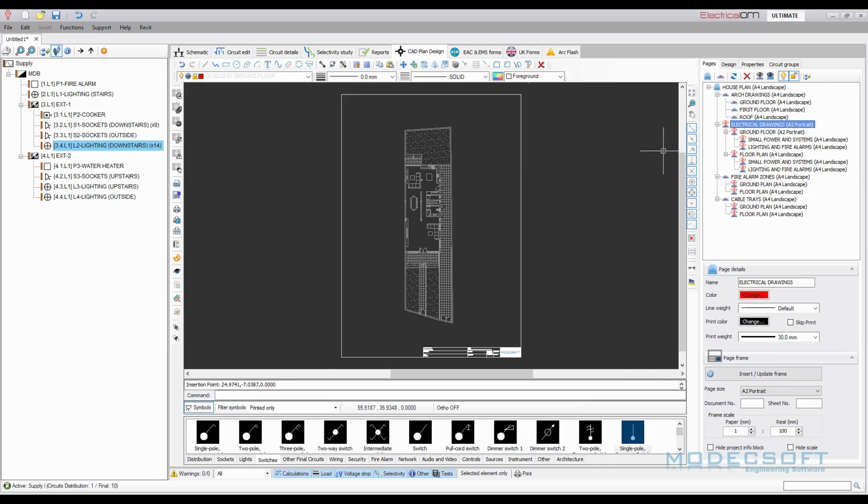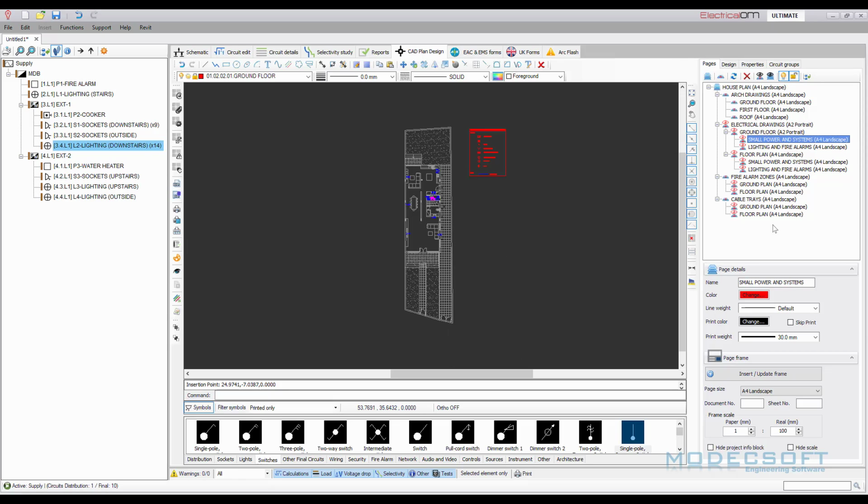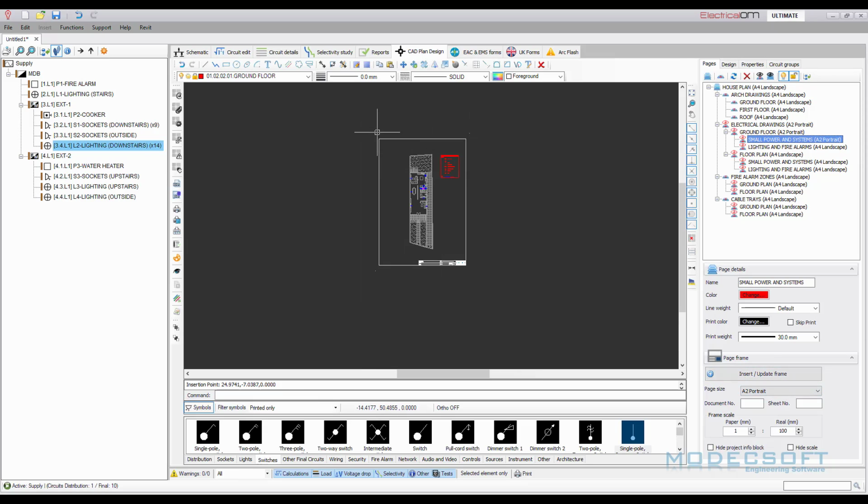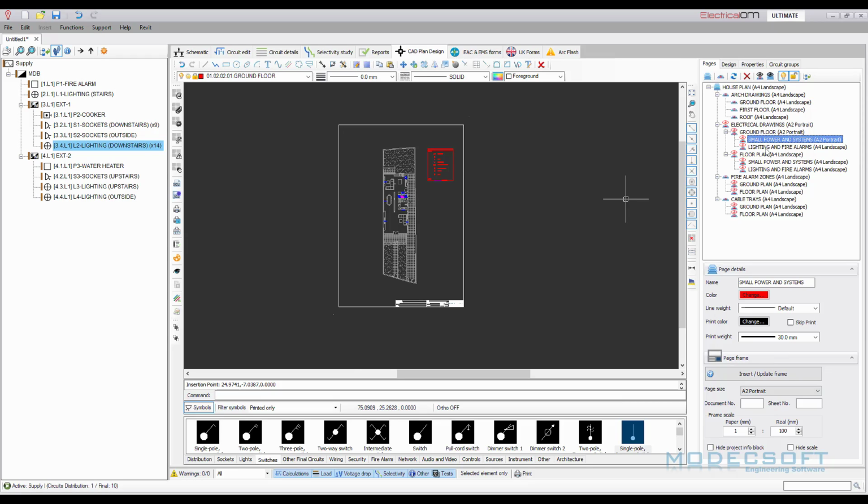As you can see, because I placed this one, and because all the external reference drawings are placed on top of each other, I can quickly move to the other layers and just select the page size and select insert, and the page frame will take the place of the previous page frame we already selected. So that's why we need to place each DWG external reference on top of each other and coordinate them properly.